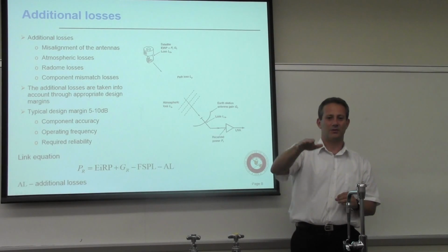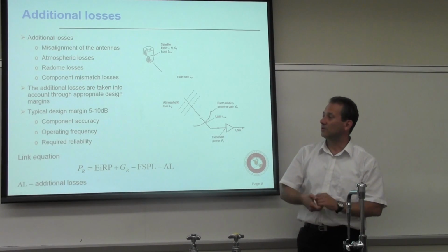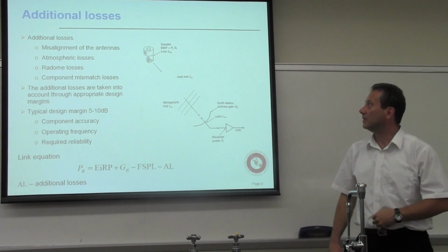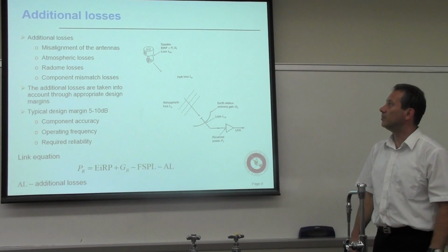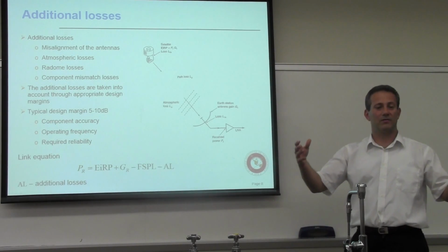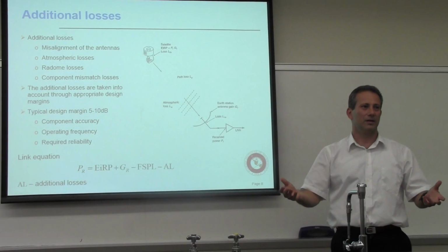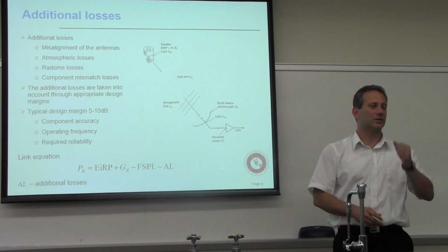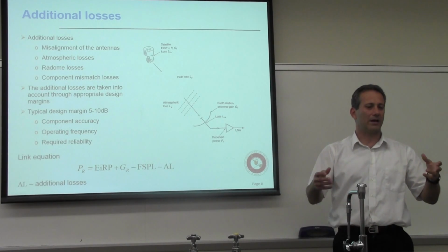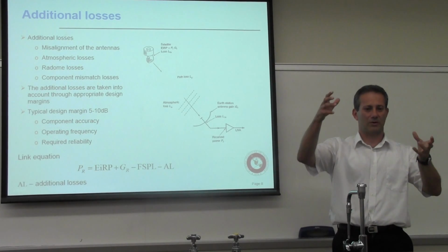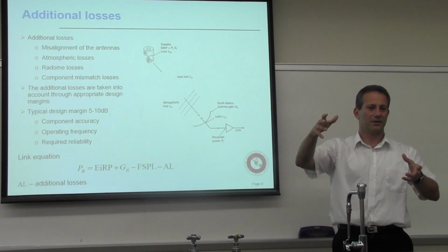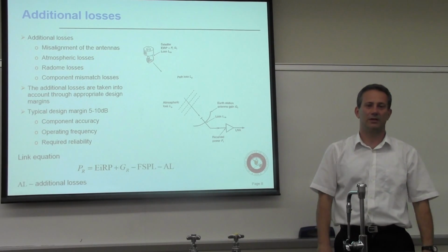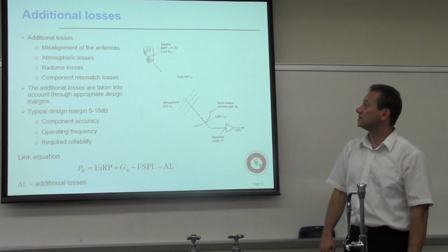So that means that you have to have the antennas in some sort of feedback loop that will help you maintain the point. Now, this is for static. If you have mobile systems, then antenna pointing is a part of their operation. If you have a satellite on the move, let's say where your dish is on a vessel, or on a vehicle, then you have to constantly make sure that the dish is pointing towards the satellite.